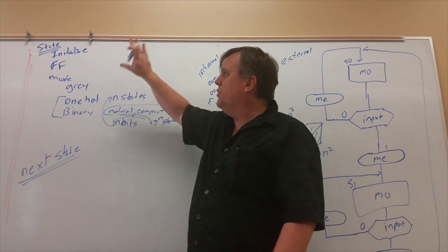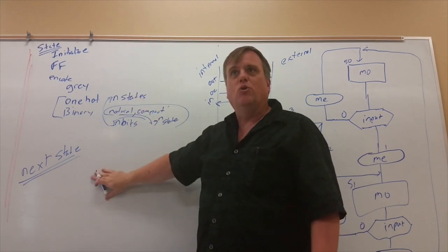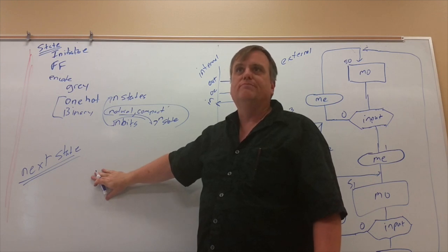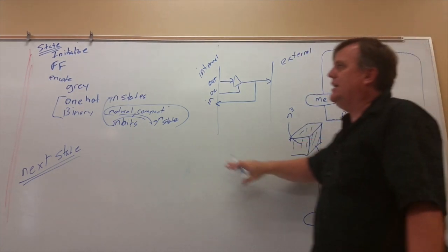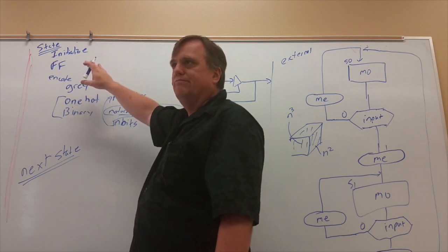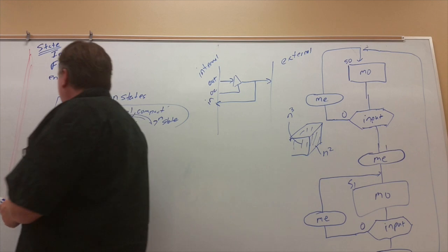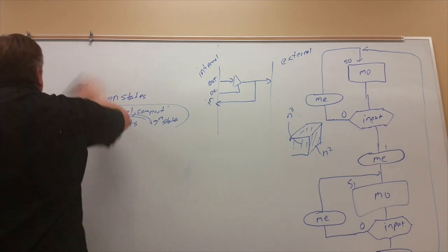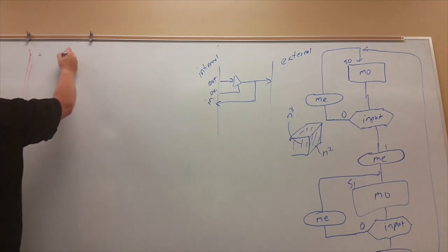We want to do this with an always_ff, and this one with an always_comb. Make sense? And we'll do what's inside the states here, and the state is just going to be a simple flip-flop. Make sense? Okay. So we're going to do that now. The state part is really trivial.